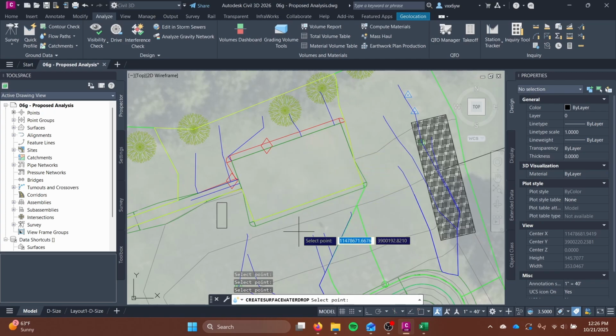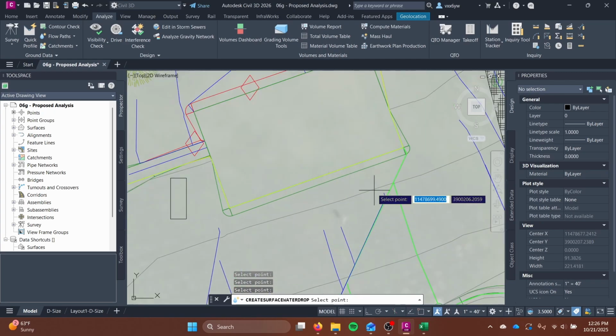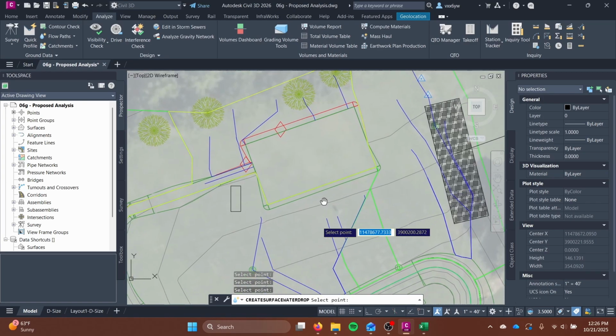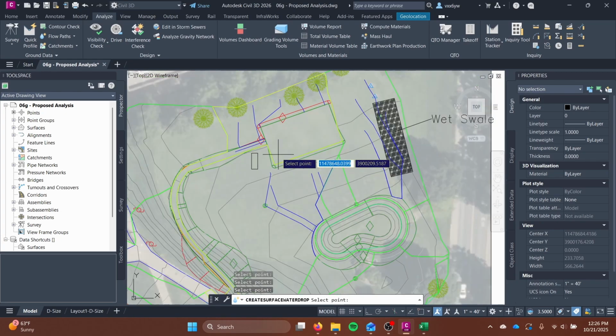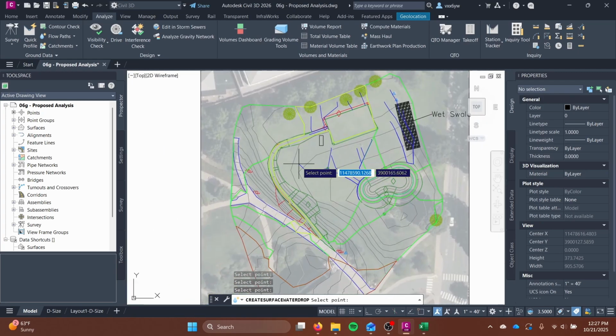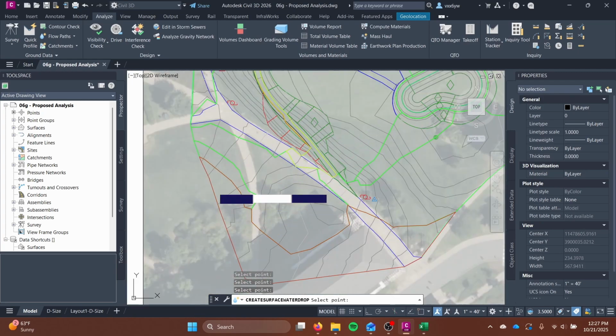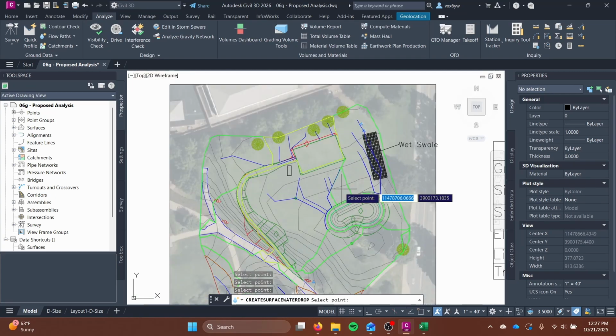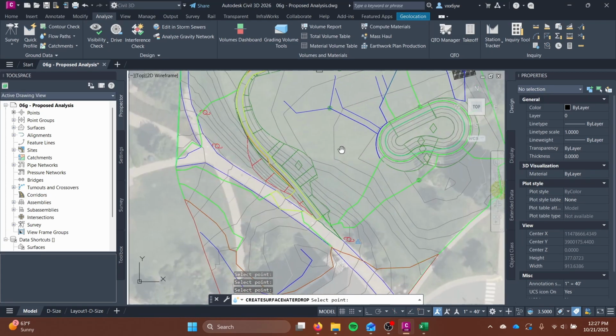Now, say I have it going north and south, but I have rainwater harvesting going on the south side. Now that runoff coefficient might be 0.6, right? So that's a way you can look at your coefficients and including this flat area in your analysis. You can also treat the concrete pad with the roof as a separate catchment area and do it that way as well. That would work too. So go through, do your water drop analysis, isolate your longest flow paths, and then from there, you can make your catchments, find your coefficients, find your areas, and calculate your total runoff.